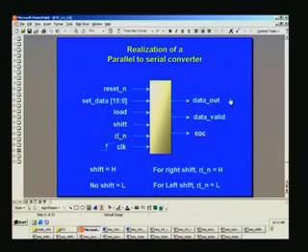And there will be a data out here which will be a single bit because it's a parallel to serial converter, and whether the MSB of the data arrives or the LSB arrives depends upon whether it is right shift or left shift. For left shift, bit 15 will go out here. We have already seen the code, so we'll look at the waveform. And there will be an end of conversion once all the bits are serviced. We also had internally one register allocated for keeping track of the number of bits processed, right?